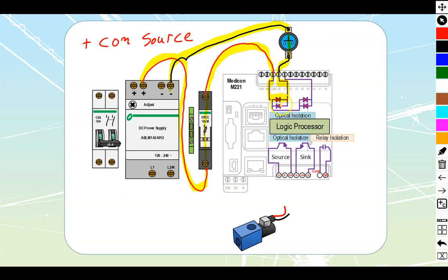Infrared LEDs that are going to give us, once again, that logic high that my processor can then read. You'll note as well, because it is for each one of these inputs, and this is a package with tiny microelectronics inside of there, it can handle AC as well, because AC is simply current going back and forth. Each of these we're going to alternate which one is lighting, so we're able to have that signal carried in on some types. Now, this type that we have over here does not handle an AC input, but you'll find it on other types of PLCs where they can handle the AC input because of that.